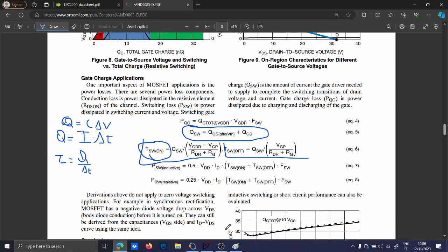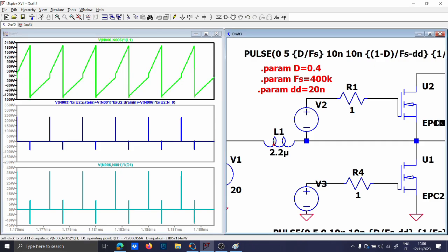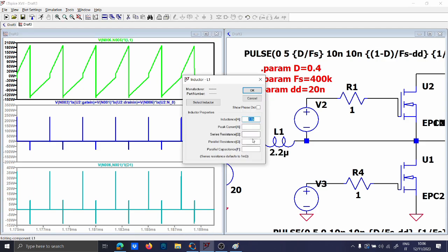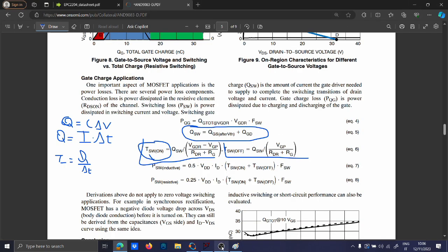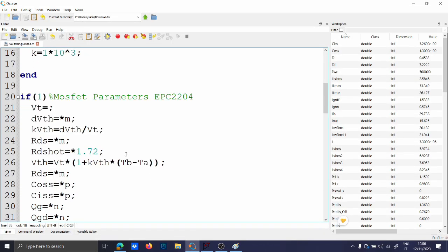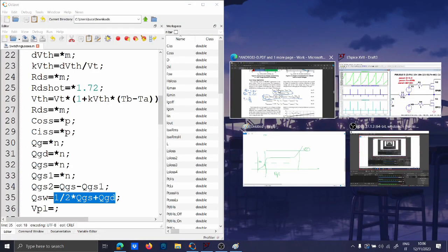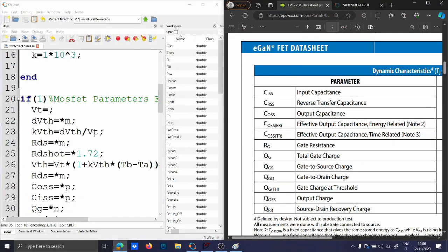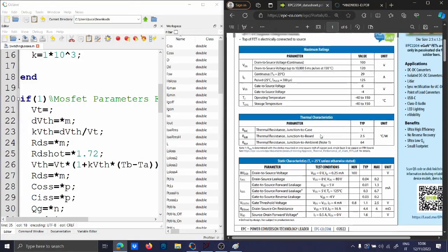Most of the losses are in the switch, in the circuit, because you see that the inductor losses are ridiculous, very ridiculous. It is true that I didn't put the series resistance, which would be 2 milliohms, for instance, because I wanted it to be very, very beautiful. But let's calculate this. Now half here and half here, and we will insert step by step everything that we need.